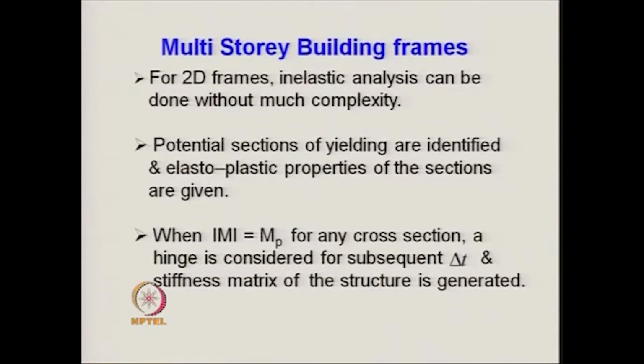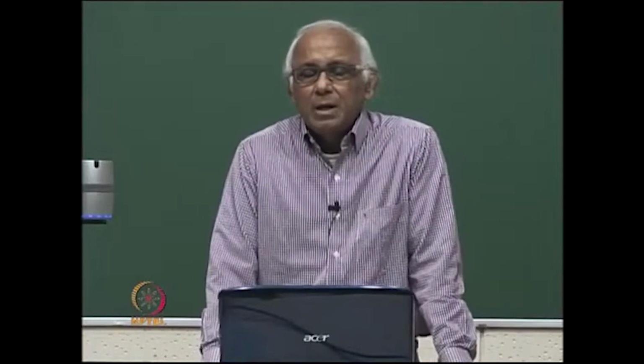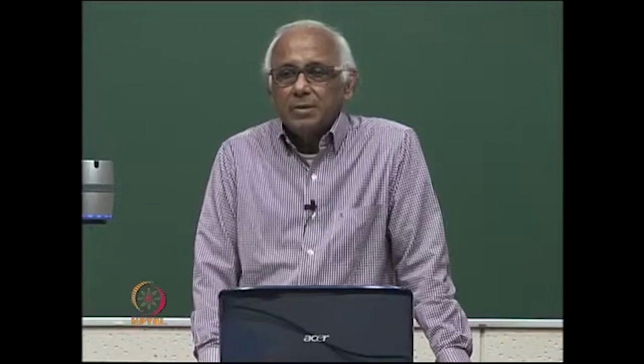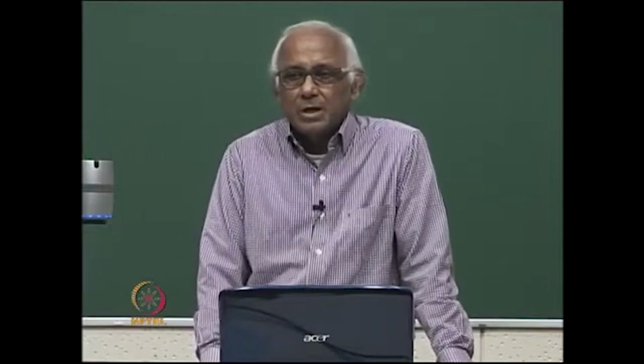In that case, we first increment the loading in small increments and apply it onto the structure, and we calculate the bending moments at the specified sections where we look for the case when the columns can undergo yielding.